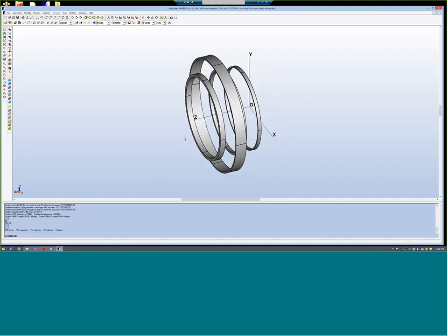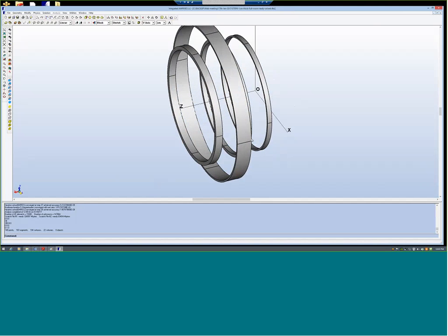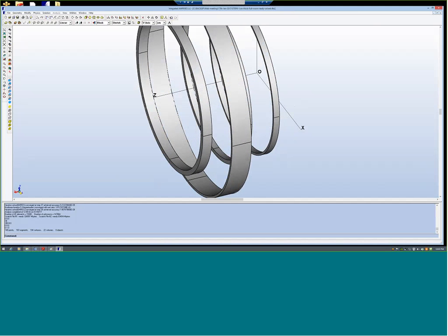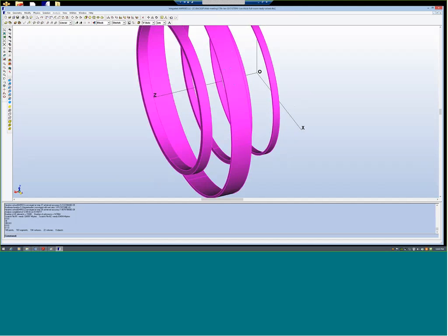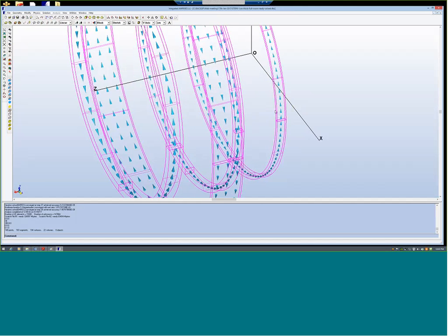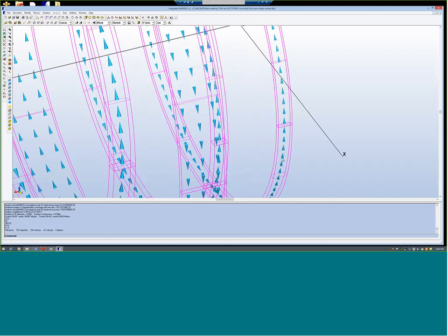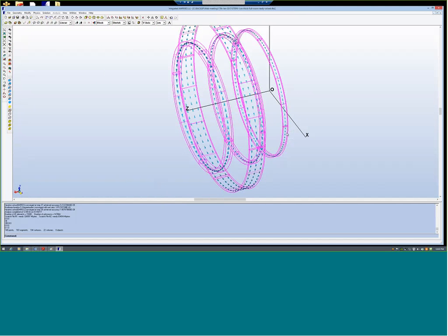So this is done. Next, there is also an anti-symmetry. What I mean is, physics, volume current. You see here, focus on this part. Whatever current is coming here, it is going in this direction. At the y equals 0 plane, there is an anti-symmetry. So I will apply anti-symmetry at the y equals 0 plane.